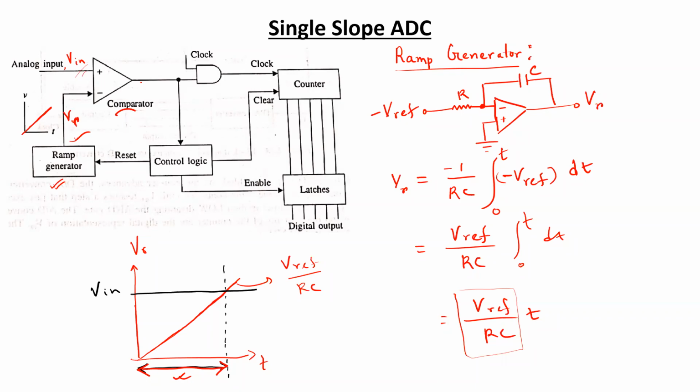Sir, it should be low signal. Why should it be low signal? I have been repeating this in the discussion of the last two ADCs as well: when you have an op-amp working as a comparator, when the voltage at the non-inverting terminal is greater than the voltage at the inverting terminal, it sends a high signal as its output. So here, as the input voltage is greater than the ramp voltage for this period of time, the comparator is supposed to send a high signal for this entire duration as well.